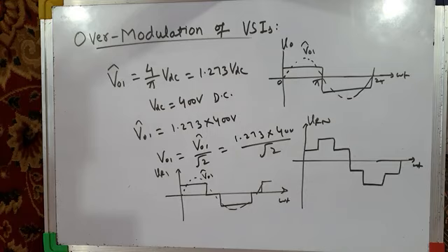And it will be very difficult to remove those harmonics. And this voltage waveform, which has a high level of distortion, is unacceptable for most applications, especially those where voltage sensitive loads have to be operated, like induction motor drives, medical equipment, microprocessor based control, and all that. Same is the case with three-phase voltage source inverters.